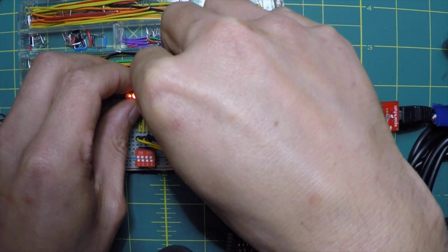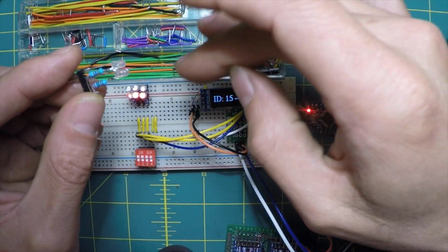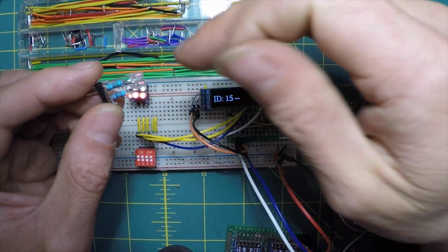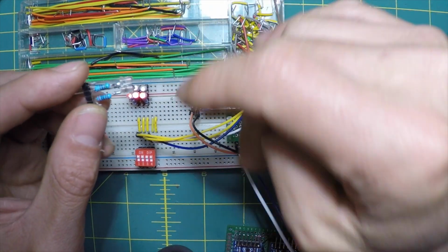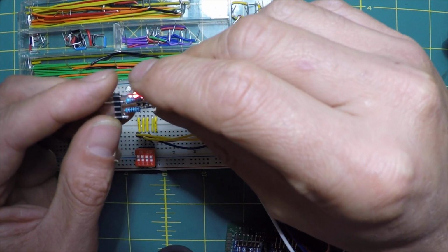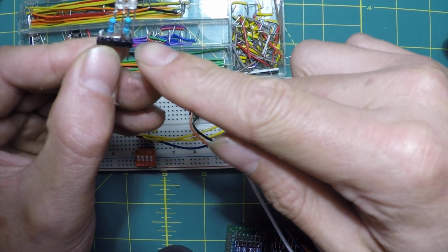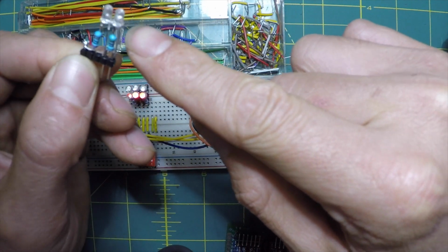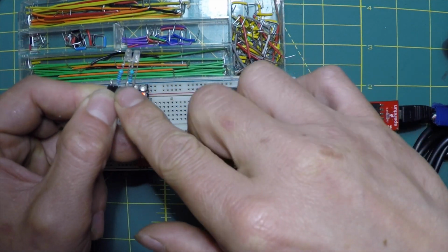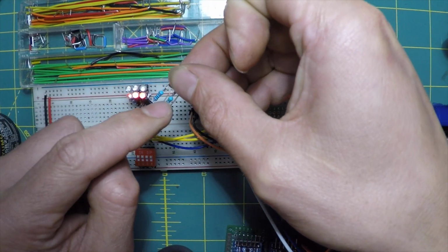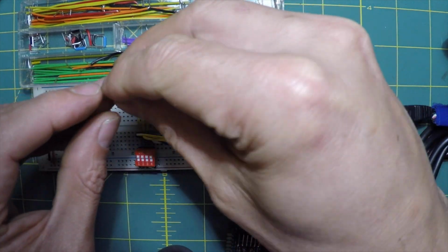And then I made these LEDs here. So basically there's a red, which is supposed to indicate off or negative voltage, and then a green that indicates on or positive voltage. And then you can see that basically they're reversed from each other. So this one's, I think, the anode, and then this one right here is the cathode. And then they're tied to 2 current limiting resistors, and then they go to a common pin.